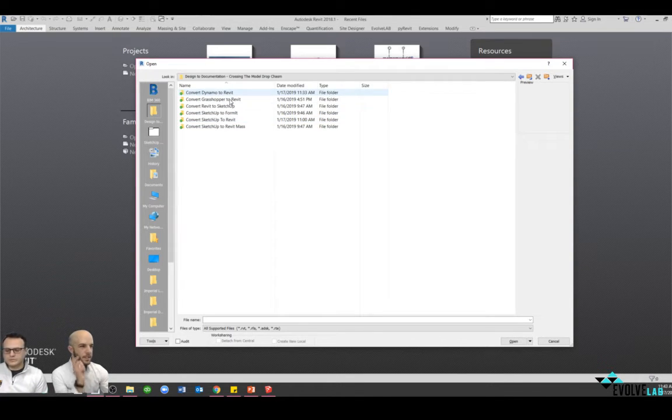The only example I would say of where I use the automatic is if I'm trying to do some kind of form finding in Dynamo, so that if I'm updating my nodes, either my integers or anything else, it's updating in real time. But for the example of pushing geometry, definitely have that set to manual, and only when you're ready to actually push it.